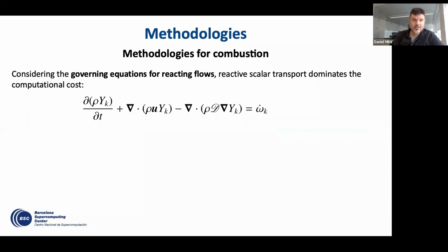So once you select the numerical method that you want to solve your equations with, you have to define what methodology you want to use to solve for combustion. Let me change the nomenclature a bit and represent the conservation equations for reacting flow with this classical expression. One of the main limitations when we want to solve this equation is how you deal with the chemical source term, because depending on the reaction mechanism, the computation of this term can be very costly, and this can introduce substantial cost in your simulations.